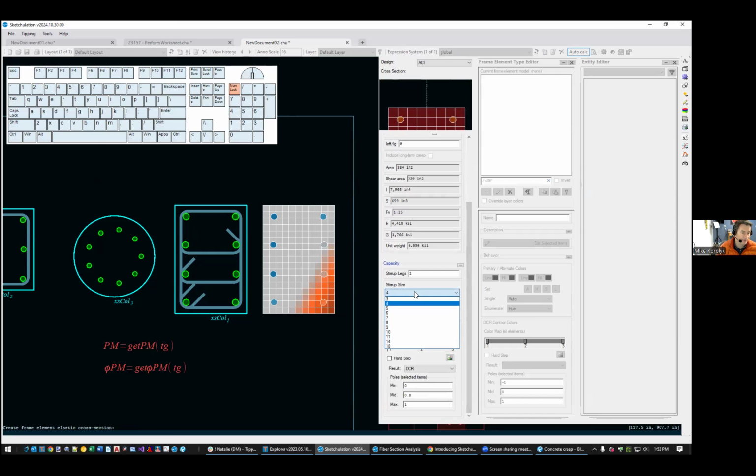So here's where you don't get a connection between the shear reinforcement. It's maybe something we could add in the future, but it's a little tricky. But here's where you would want to make sure that these things match up. So set your spacing, set your stirrup size, and then number of legs. So 2 in this case in one direction.